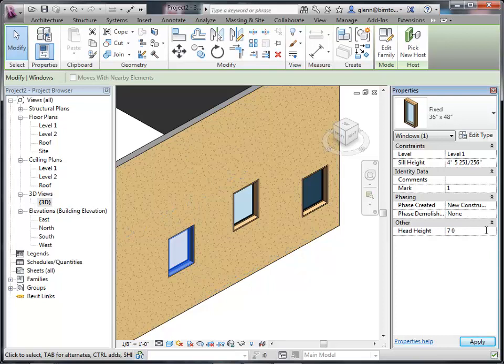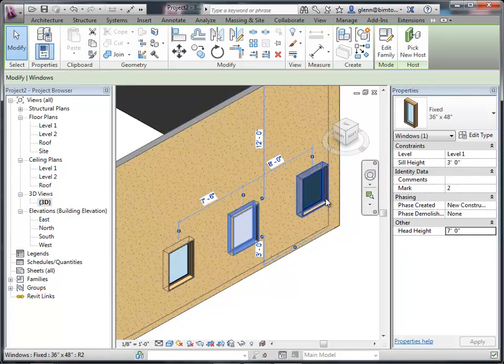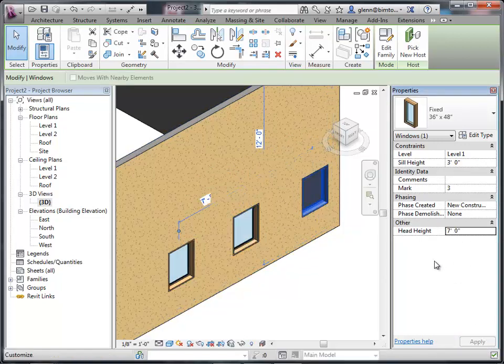Think about this: on every different structure these days, there almost always is a uniform height for the heads of the windows. It often matches the same as the top of the doors. It used to always be 6'8", but more recently we do things more at 7 feet or 8 feet, depending on architectural effects we're trying to achieve. If you need to change the windows, you can change them after the fact just by typing in values and getting them to come up to the right level.